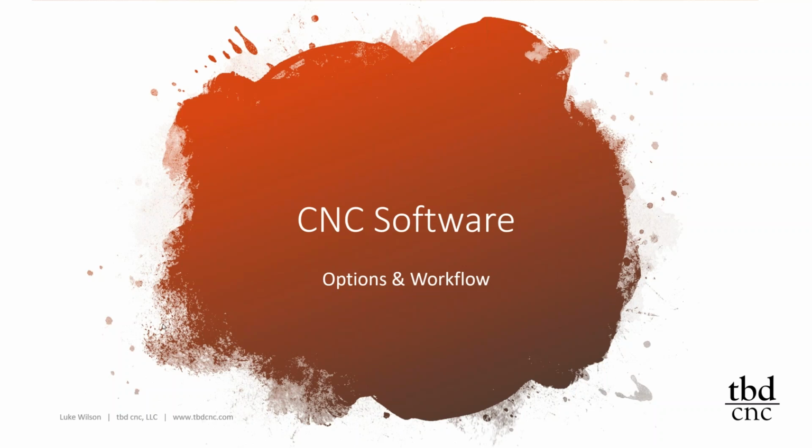I keep it as a separate pocket, so I just drag down the bits that I actually have, but it's all their specs. They're really aggressive with their defaults, so I usually have to ratchet those back, but the descriptions are in there, the sizes, everything's there. I don't have to mess around with it. You just download, import the database, and then, like I said, you drag the bits that you have or want to have further down into your tool database. That's one of the reasons why I like Tools Today and the Amana bits in general, because it lays it all out for you.